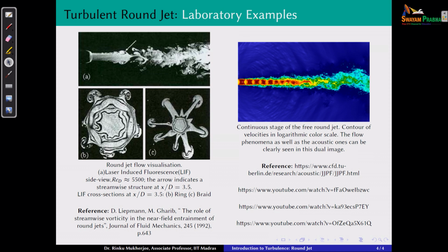So if you have a laminar flow, all the fluid particles are essentially moving in the same direction. That's why we have nice little laminar flow, or at least, if I'm able to draw some specific lines, or track the path of these particles fairly well, then at least it's something that I can understand. But here things seem to be very complex and complicated, and this is happening because the fluid particles are moving in such ways that they're forming, say, the ring or the braid.